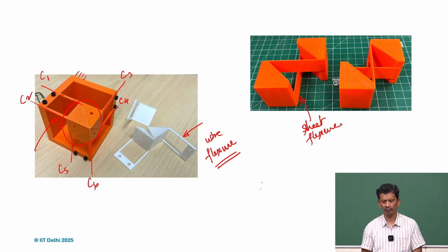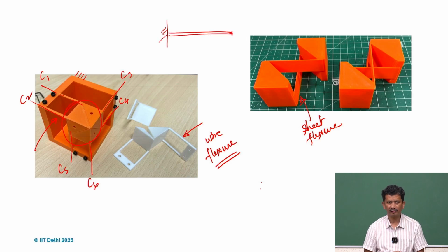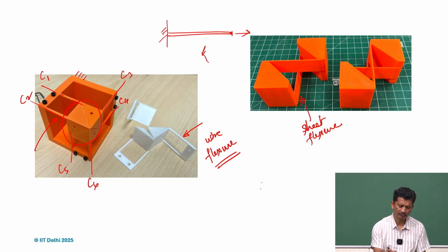And yes, we use a pair and we can make cross flexures, which will act as a hinge, or if they are in parallel, then we can design parallel guiding systems. So in the 2D case, what we realize is that it is just a very slender element. Under tension it is very effective, and the stiffness we are talking about will be EA by L.